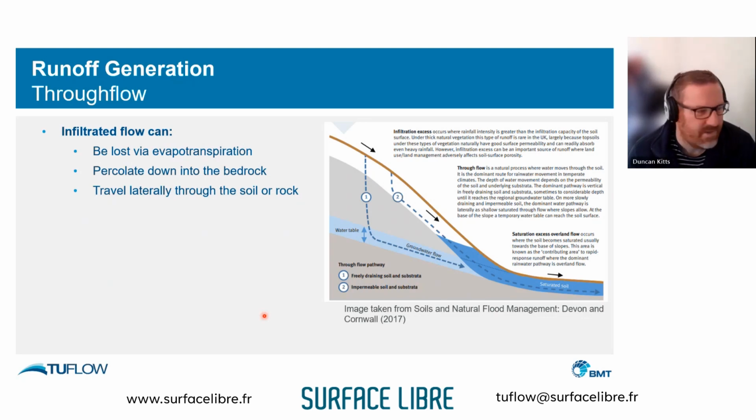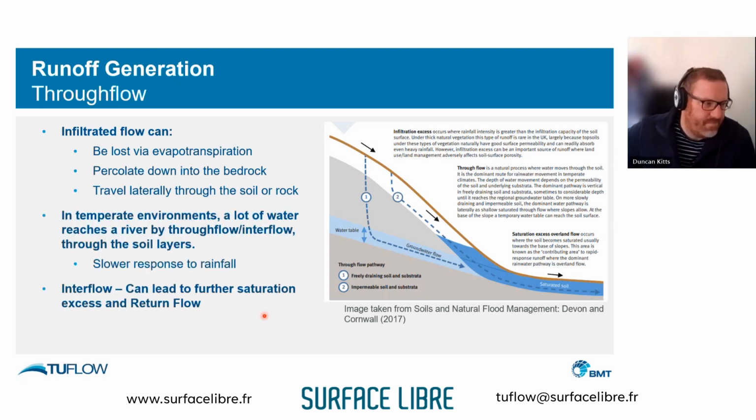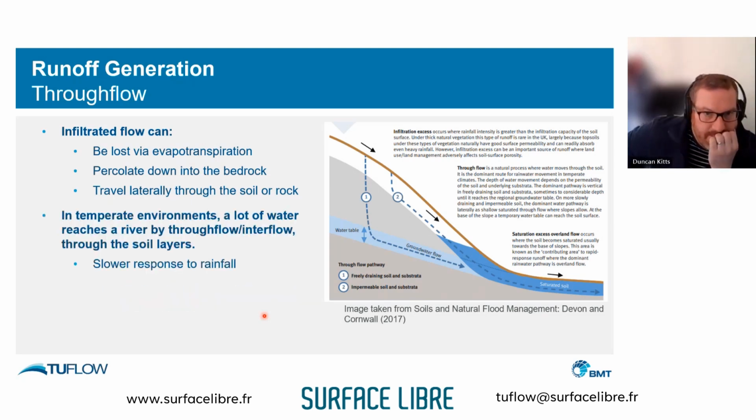If we want to do very simple models with just a specific percentage for each soil or land cover, we use 2D RF polygons. And if we use this fraction in conjunction with an infiltration model with infinite infiltration with dummy values, can we get the same?